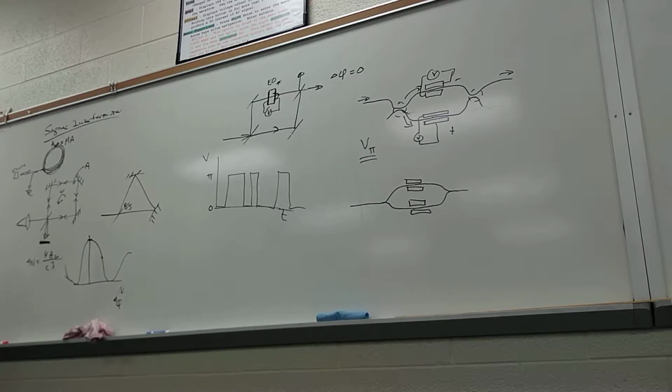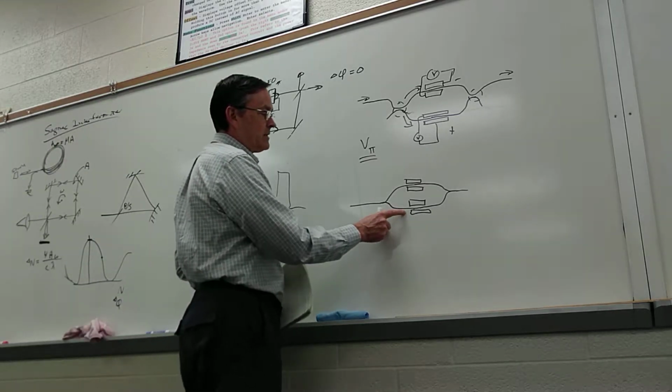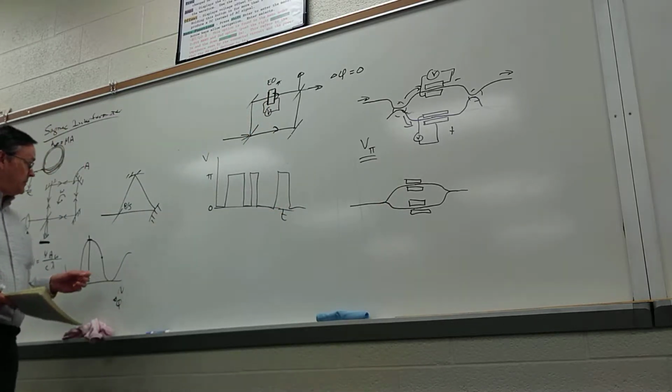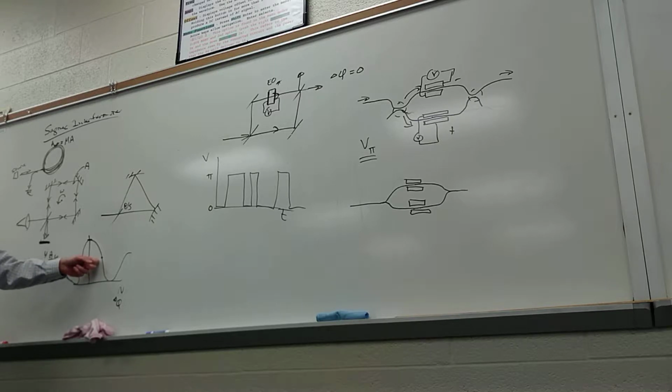And in fact, with a Mach-Zehnder modulator, it's the same deal. You really want to be sitting there and not there. So what you do very deliberately is you take one of these path lengths and make it longer than the other one, so you're biasing at pi halves, because at 0 or at pi, you basically have no sensitivity for small changes in phase. So, yeah. All right.